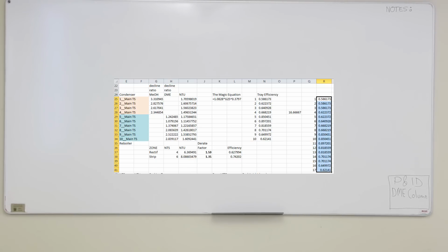So what I did here is I took the average, which is about 0.6 tray efficiency, and then prorated my calculated efficiencies from his number of transfer units into a bunch of stage efficiencies here, just to give me a little bit better sense of what the temperatures are through the tower. So hopefully that'll be a little bit helpful as I'm going through it. And how I do that is, sorry, the screen's a little bit small, so I just scroll back and forth here.